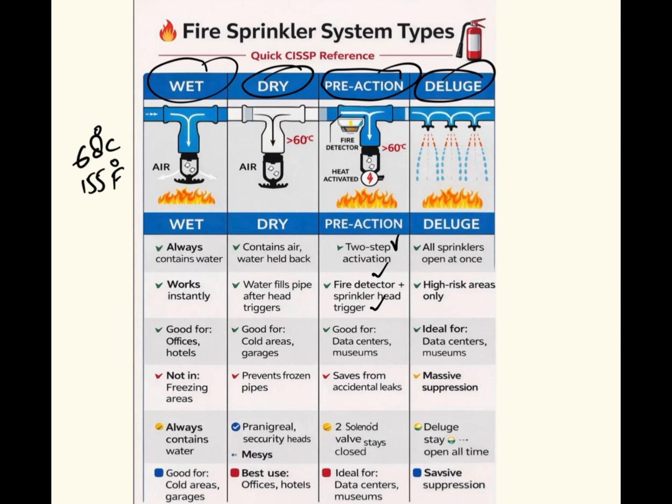relatively simple and fast. Dry, for cold areas. Pre-action, safest for assets, with risk if detection fails. It is very helpful if there is a false positive, right? Deluge: detect, dump everything.